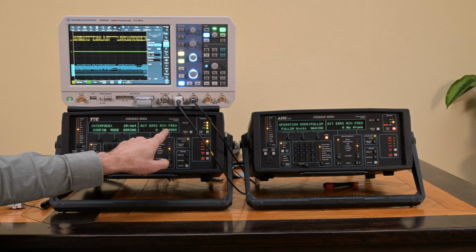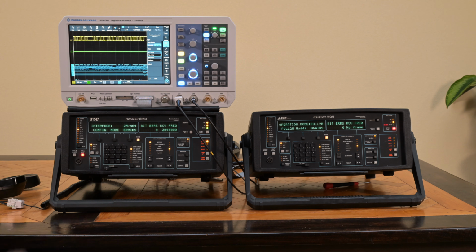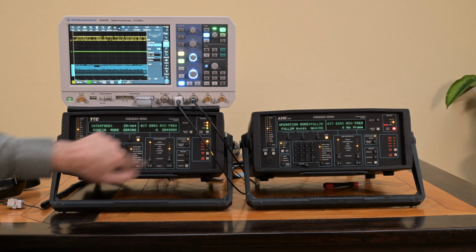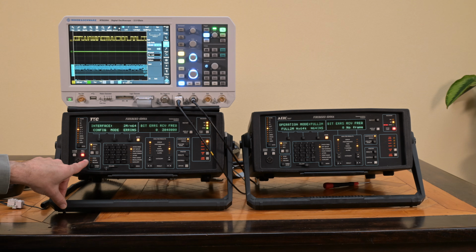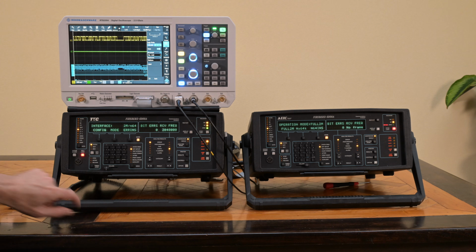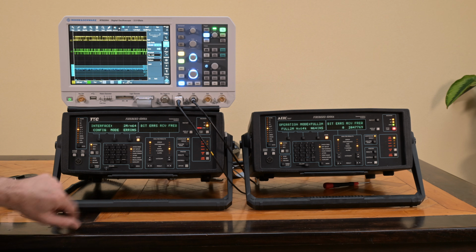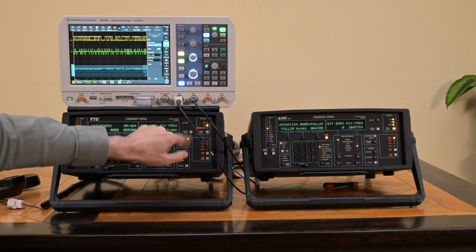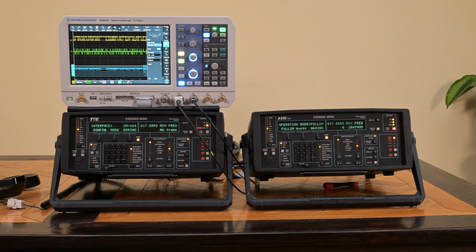There's a signal coming in at this internal analyzer of 2 megahertz, or 2048 kilohertz, and that is the clock frequency defined for the E1 trunk line. But since we're getting it here, that means we're still in the internal loop, and indeed the self loop is activated, so it's not sending anything there, it's just keeping the signal looped inside. So let me go and send it to the second unit. We see the signal disappearing here, there's no clock, and on the second unit we indeed see now that there is a signal coming in.